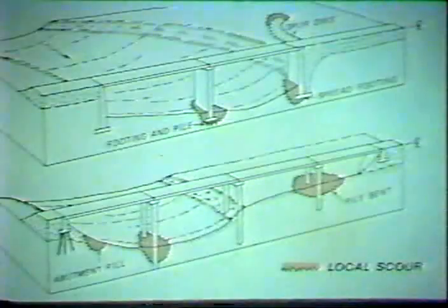and was attributed mainly to eddies in the bridge waterway. Flow distribution in the waterway during later floods was much improved by the installation of spur dikes. Effects of channel degradation attributed to gravel mining are shown at this county bridge on Cache Creek in California.